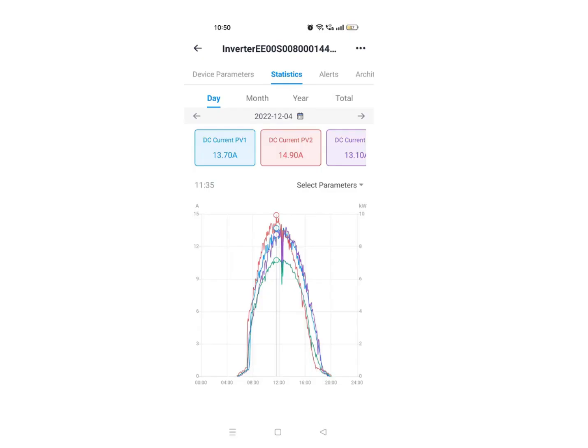In the photovoltaic power generation system, the solar irradiance gradually increases from sunrise. The voltage generated by the power generation module also increases slowly. When the voltage reaches the working voltage of the inverter, it starts to work and the whole system enters the power generation state. When the photovoltaic panel's voltage continues to rise and reaches the voltage operating range of the inverter, MPPT will adjust the voltage to the maximum power output point voltage so that the string of panels tracked at each MPPT generates the maximum power.